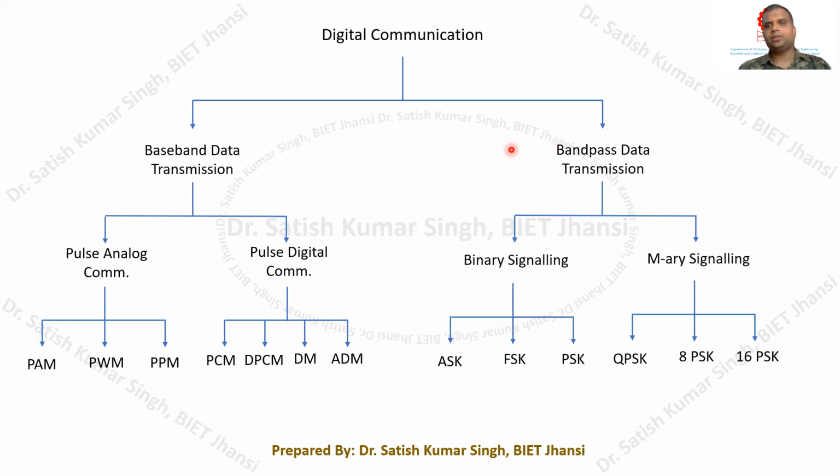Here we can see that in the case of band pass data transmission, after having a digital message signal, that message signal has to be multiplied with the high frequency continuous wave, a high frequency sinusoidal carrier. But in the case of baseband data transmission, there is no such requirement. Remember that here we just have the pulse, and that pulse has to be modulated in a certain way.